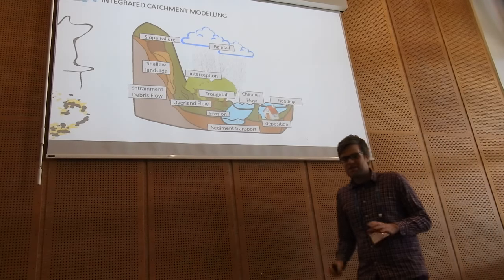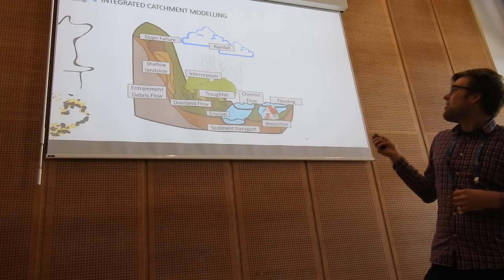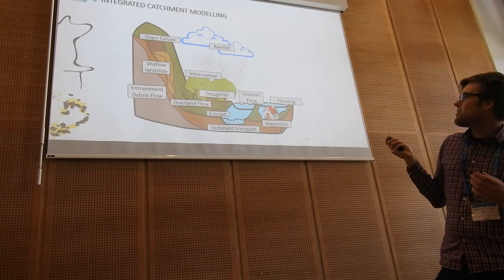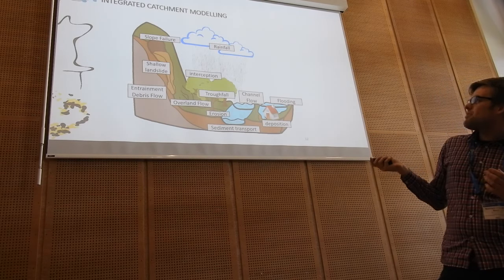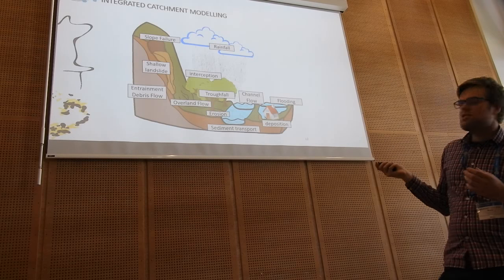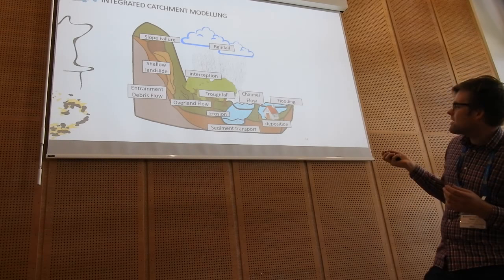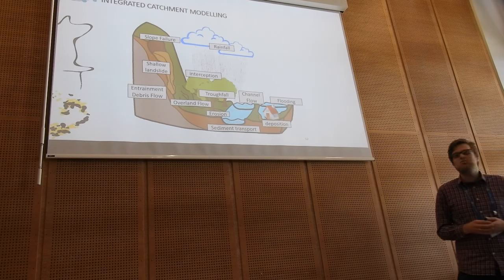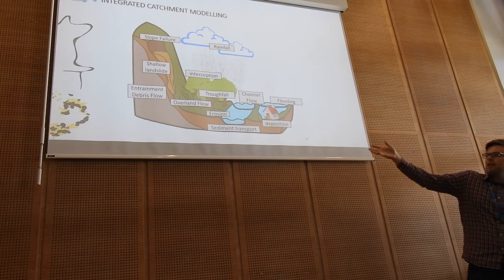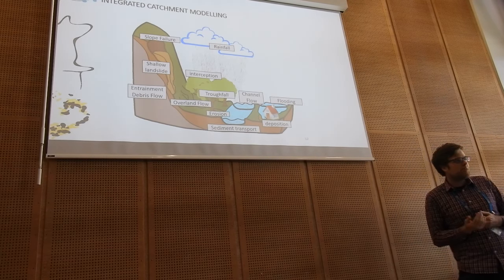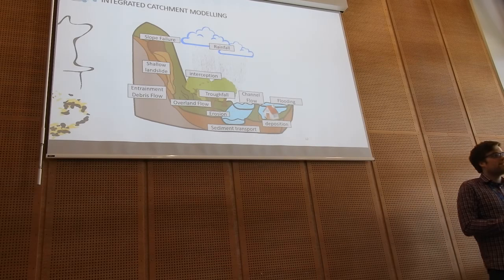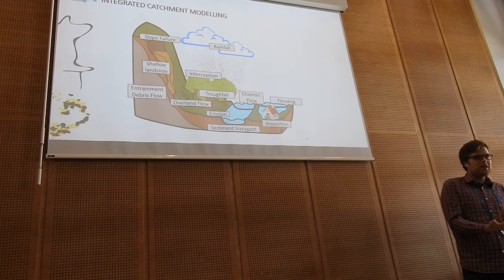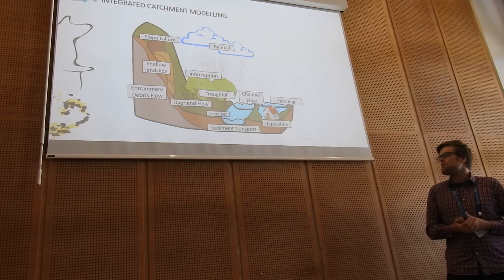Okay, so this is the schematic view of what we wanted to achieve here. So the processes we currently have in there that are all interacting and working. So from rainfall towards full catchment hydrology, infiltration, groundwater stuff, we have the channel flow, the flooding, sediment transport, so erosion is also in there. OpenLISEM started as an erosion and hydrology model. And we added then shallow landslides, automatic volume estimation, the runout, and the runout is two-phase, so it can have water and debris and rocks and stuff, all mixing, and that interacts also in a natural way.